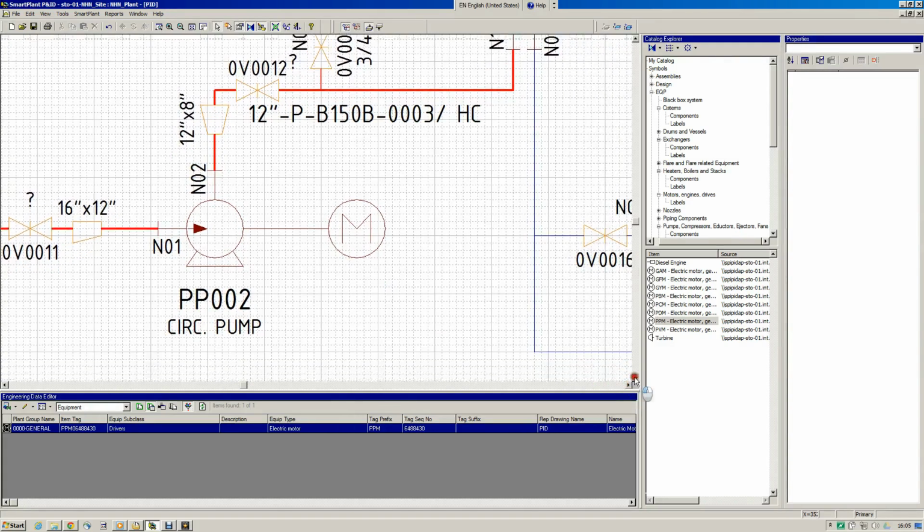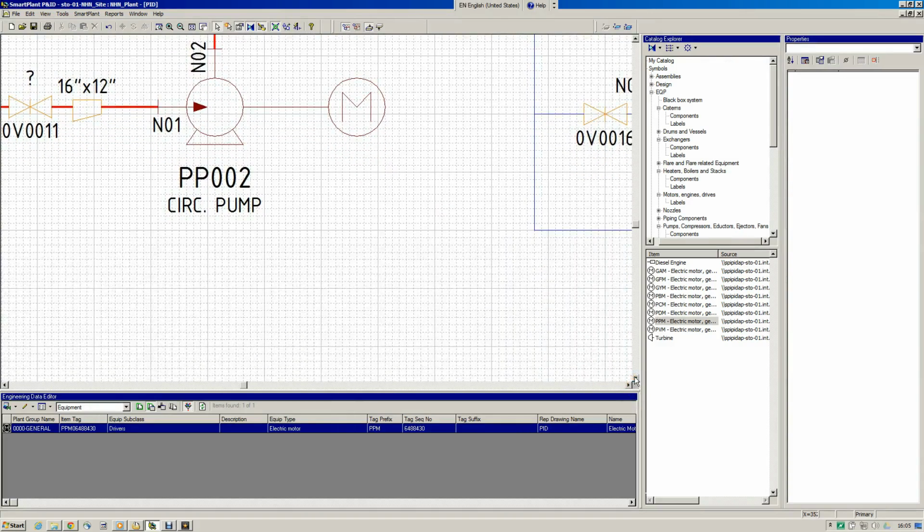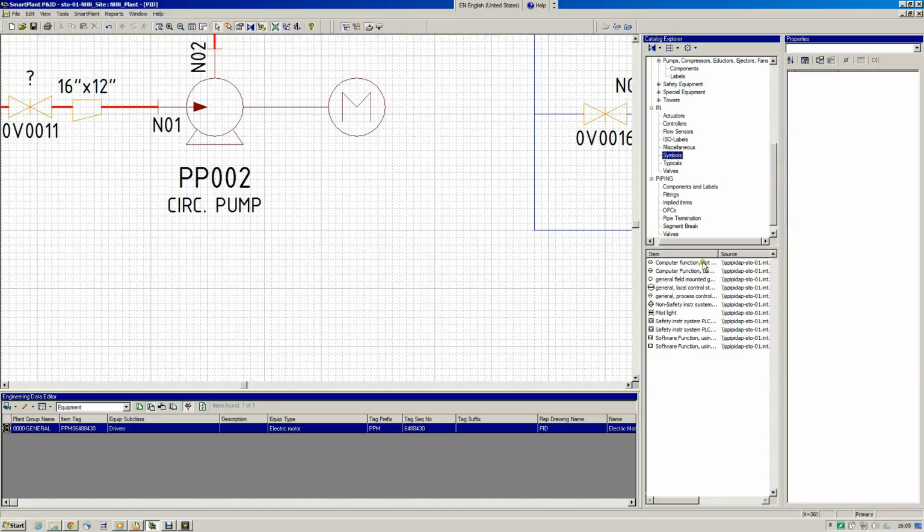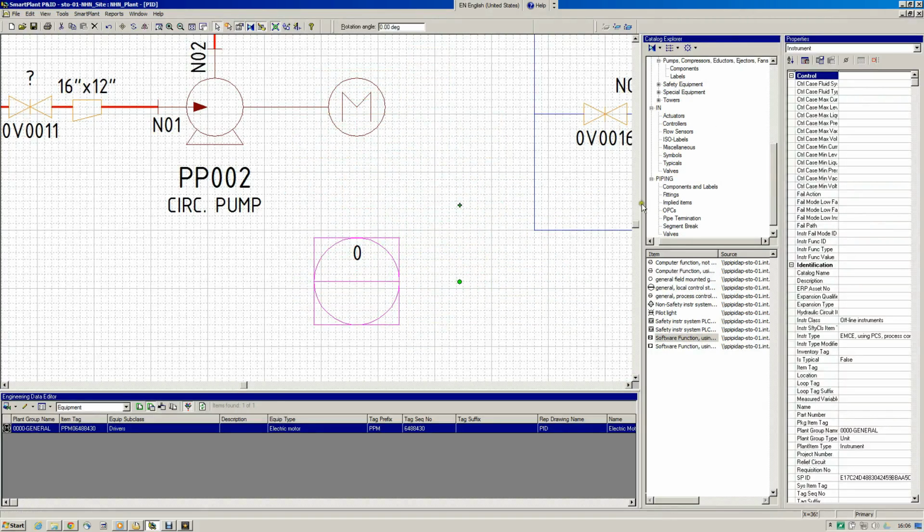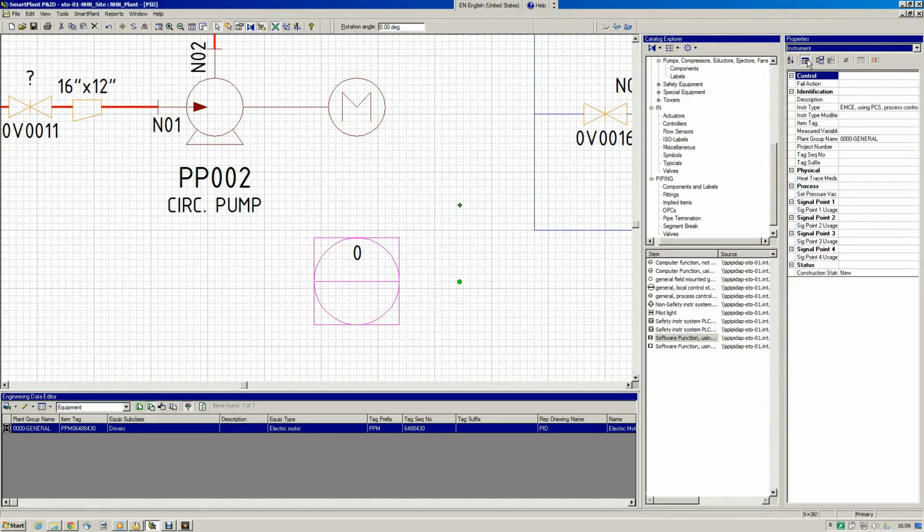We need then to be able to start and stop the motor. Okay, then we need some instrument. Or actually we need a connection to the DCS. What connection then? Yes, we need a Handswitch. So we have a measured variable that is then H, and we have a modifier S, like this, and we have an operator line to this then.